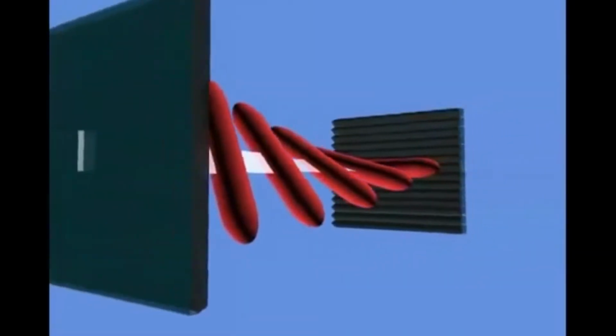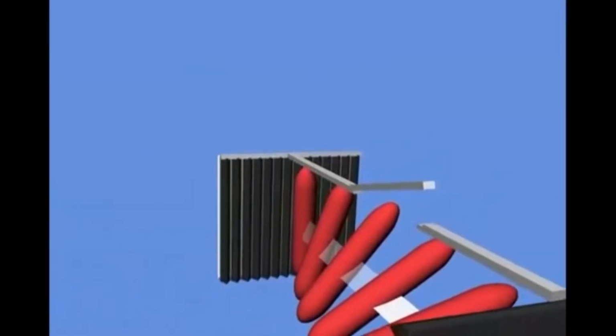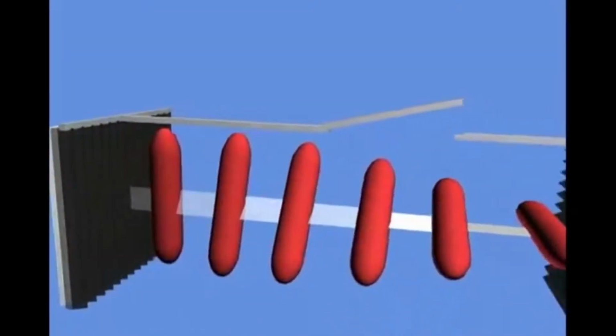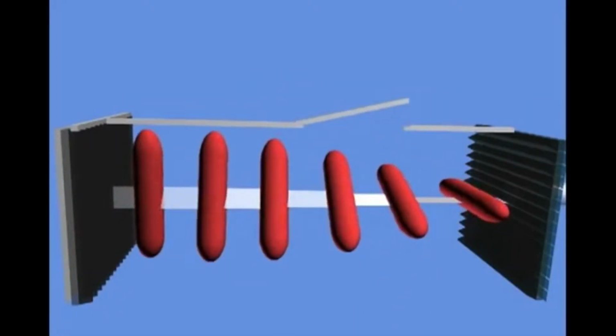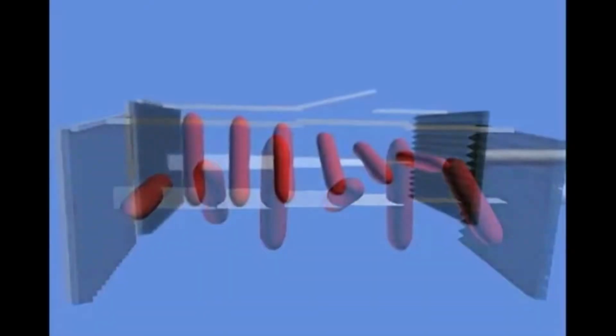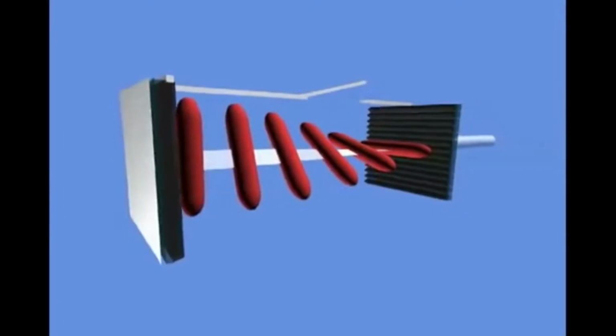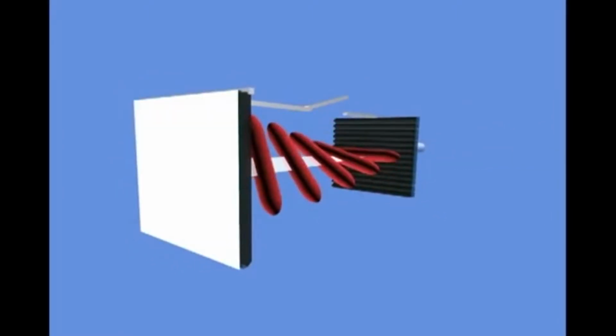If an electrical field is then generated between the glass plates, the special property of the liquid crystal molecule becomes fully apparent. As the molecules are dipolar, they react to the electrical field and are repelled. The rotated molecule structure is interrupted. When light then passes through the first polarization filter and follows the direction of the molecules, this hits the outer polarization filter and cannot pass through it.